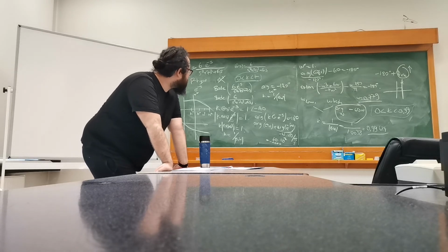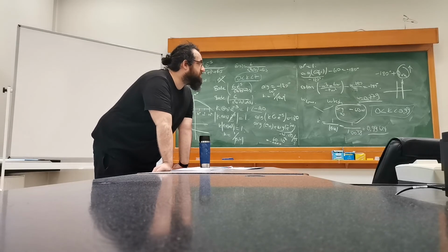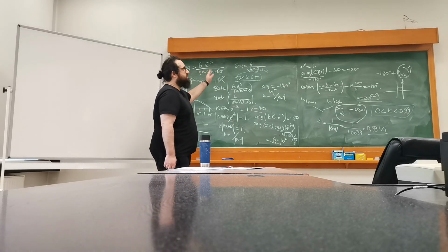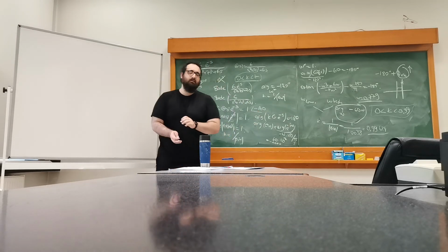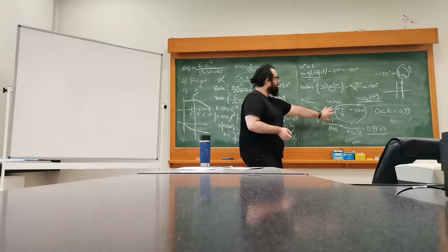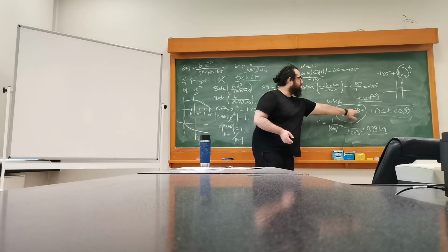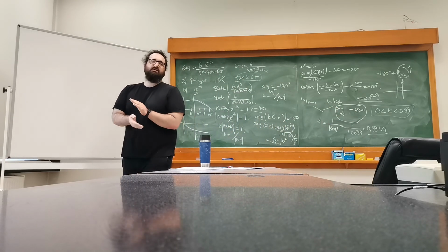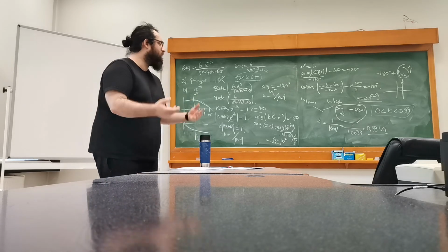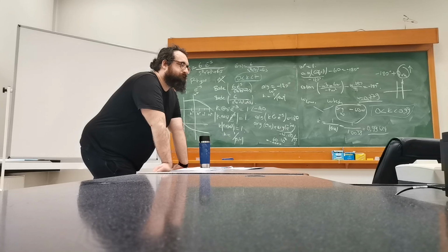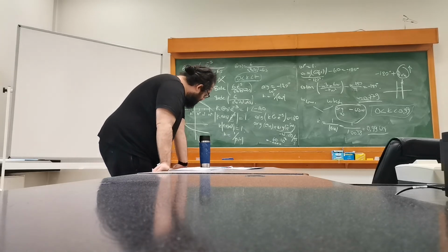And for this system, we can see that adding delay decreases the stability interval. If you, for example, add 0.5 seconds to it, you will have a greater k value there. It's just obvious based on the fact that you will use this relation here. And this will not be 60, it will be 30. So you will hit this 180 degrees margin later. And therefore, your gain will decrease and your k will increase. So that's basically question 5.